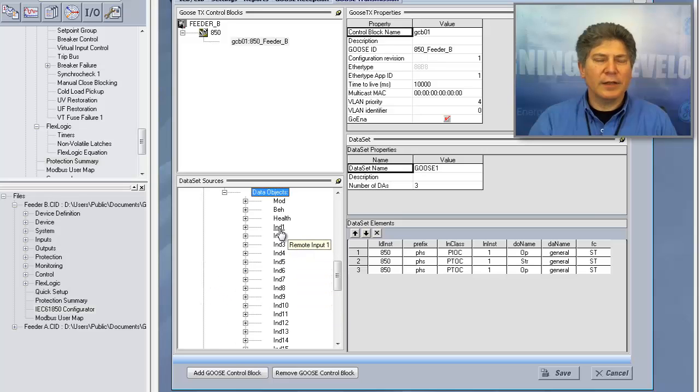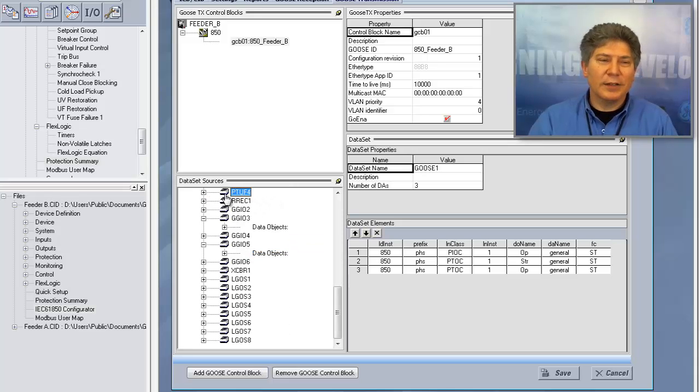I think these are different in the remote inputs than in the UR, because the UR is different, eh? It is indeed. In the UR, we're actually using GGIO1 as well. So GGIO1 was the publishing. GGIO3 was the subscription. GGIO4 on the UR was different.